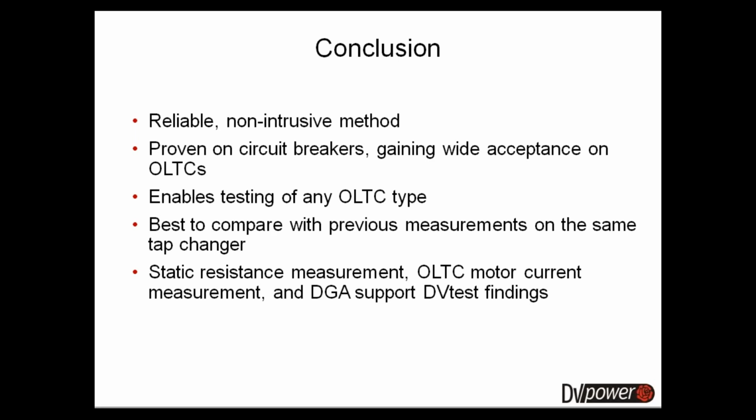So the DVTest findings can be confirmed and supported by other tests, such as measurement of tap changer motor currents, measurement of winding resistance in various stationary contact positions of the tap changer, and also by dissolved gas analysis.